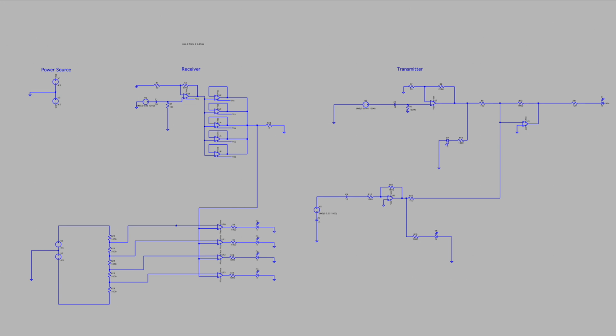For my transmitter circuit, on the bottom I have my aux, where it is connected to a capacitor, and then it is connected to a voltage source, which is obtained from the aux, and then it is going into another capacitor, and then there is a feedback loop op amp, where the resistor on the top of the feedback loop is a potentiometer, and then there is an LED coming out from that output, which would be the mic or the aux indicator LED.